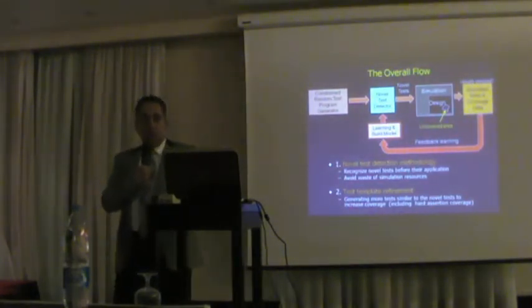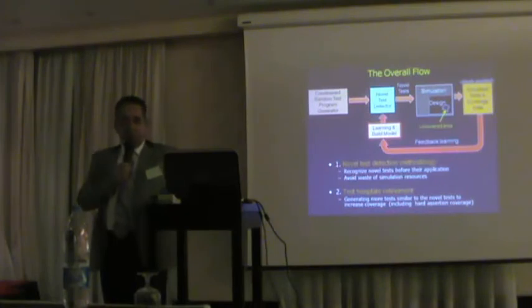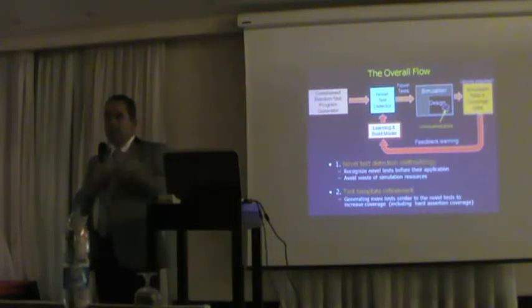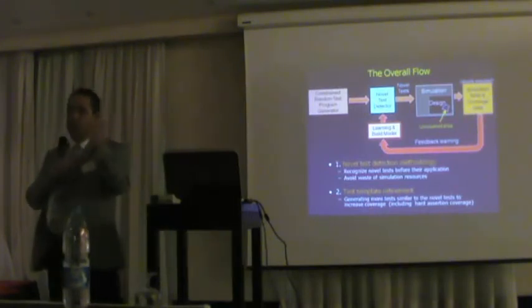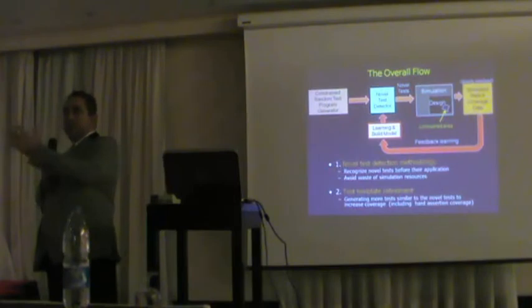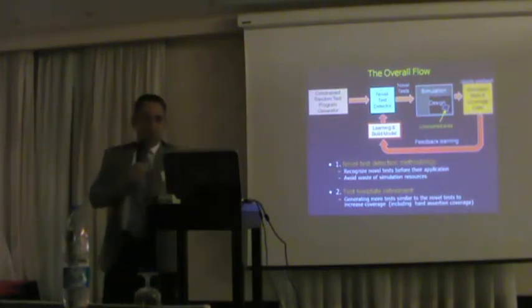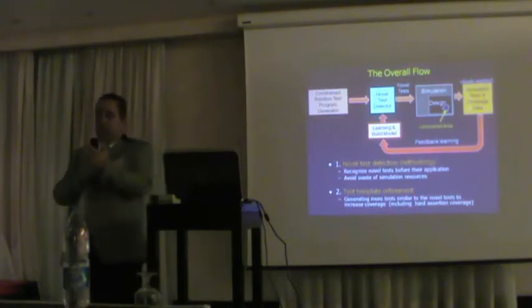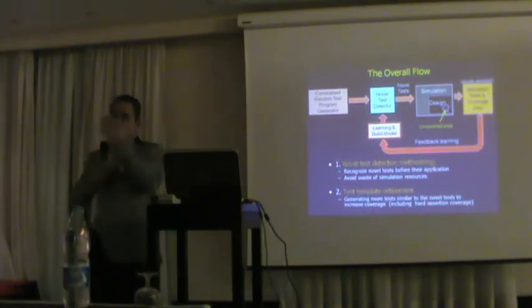One of the approaches people use to run these simulations is what we call random generators. They generate random tests or random inputs, and then simulate them. When you simulate them, what you're looking for is something that catches bugs or improves the coverage of your simulation. Now you're running